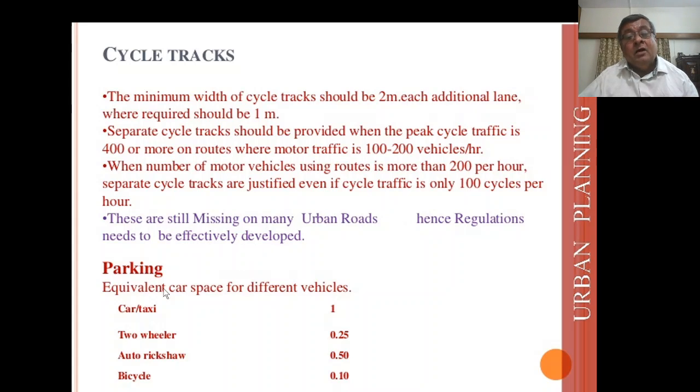Parking, equivalent car space for different vehicle. For car and taxi, one parking slot should be provided. For two-wheeler, 0.25 area should be provided. For auto rickshaw, it should be 0.50, and for bicycle, it should be 0.15 space should be provided.